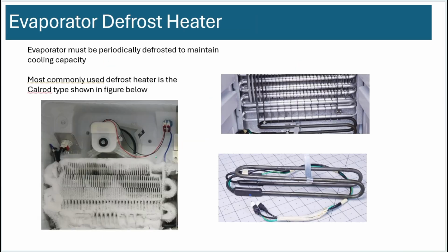This is why. So in a refrigerator, the evaporator operates at really low temperatures, okay, much lower than minus 20 degrees C. Okay, so it could be minus 35, minus 40, minus 30 in that region. The air conditioning evaporator operates somewhere in the 5 degrees C or above, so greater than 5 degrees C. So this has a lot of chance of icing. Okay, you can develop a lot of ice and frost in refrigerator. You don't have that issue.